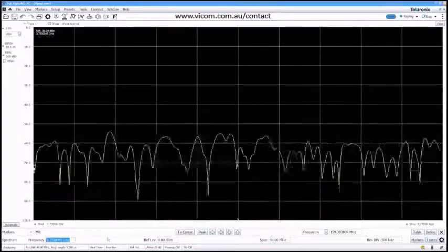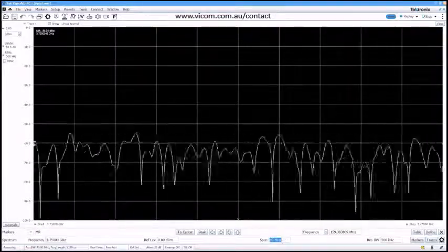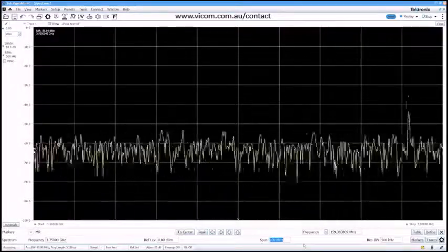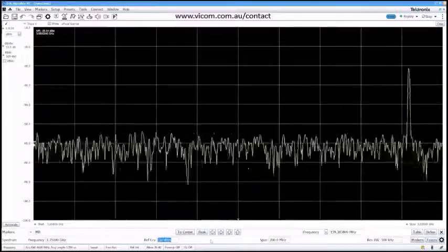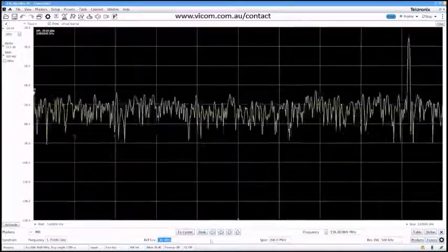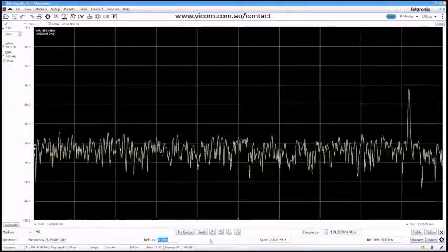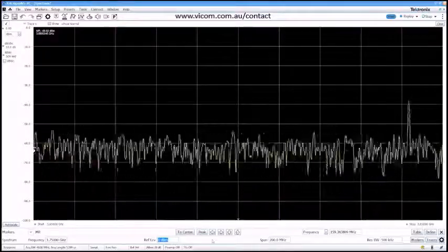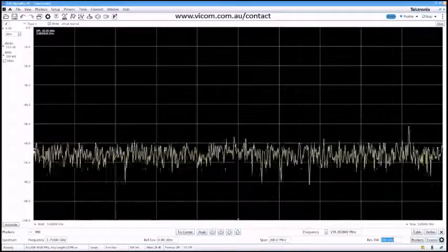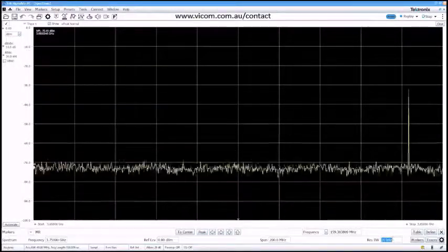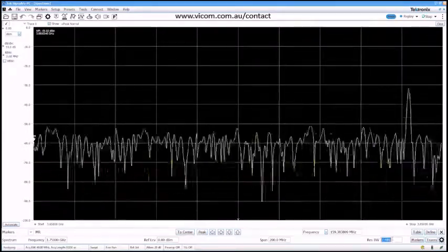Center frequency sets the location and frequency to which the analyzer is tuned. Span determines how much spectrum around the center frequency the analyzer can see. Reference level adjusts gain and attenuation settings in the signal path, allowing the analyzer to capture stronger signals without overdriving and see weaker signals with a better signal-to-noise ratio. Resolution bandwidth determines the smallest frequency separation that the analyzer can detect and has a strong effect on the noise floor of the spectrum display.